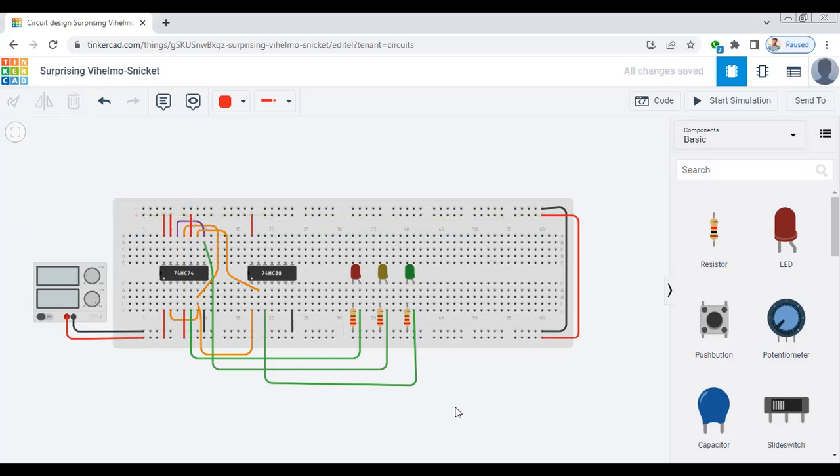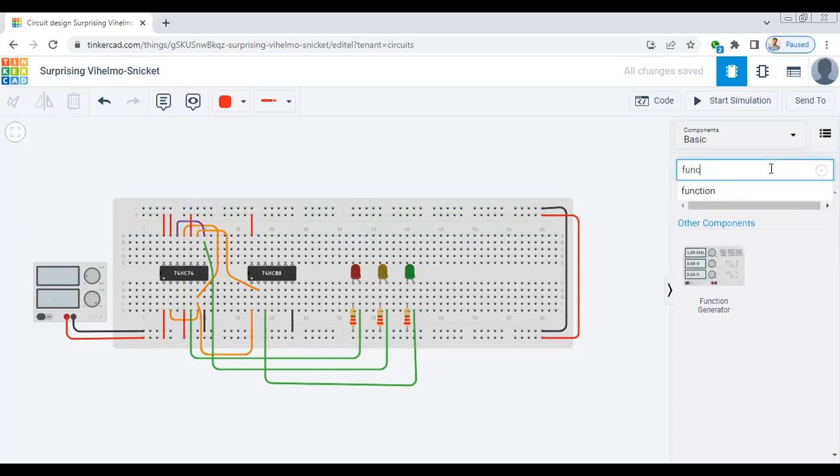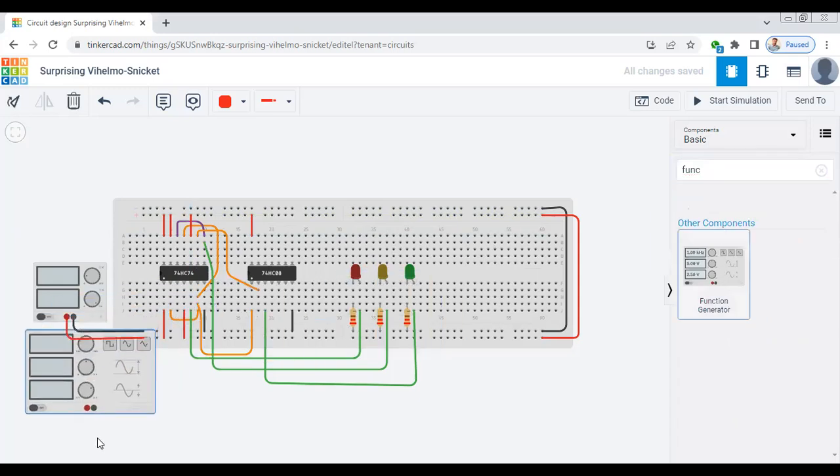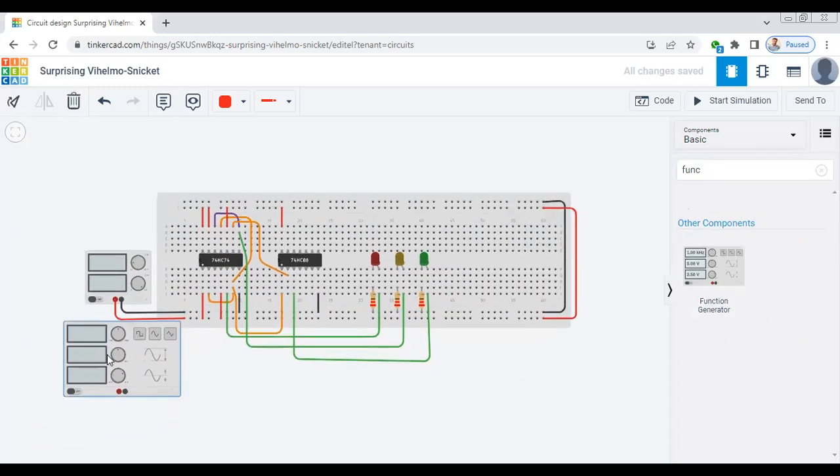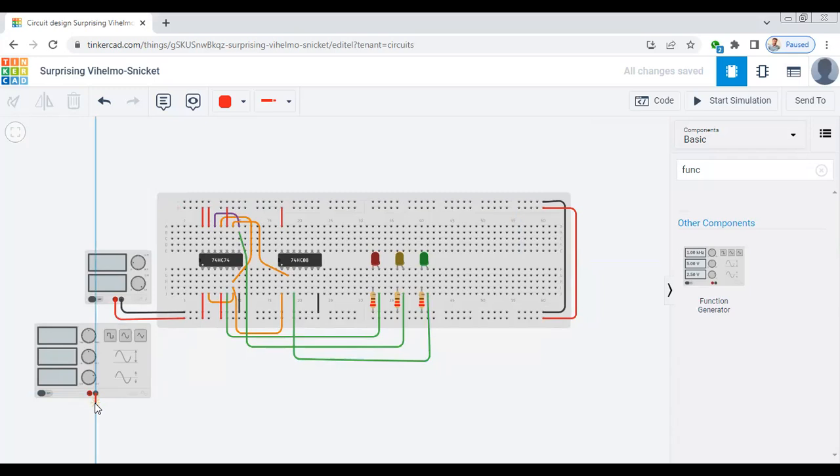And after that, now one component is remaining, that is our function generator. We are using the function generator here for giving the input pulse. In the function generator we have 2 terminals. The negative terminal of the function generator, we connect it to the negative layer of horizontally shorted slots in this manner,